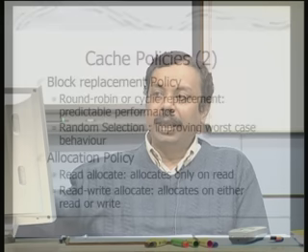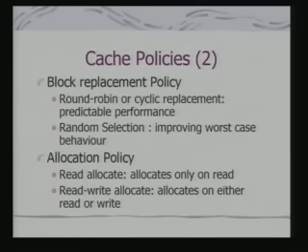So, in that case, even when there is a write operation, you would like to allocate that block in cache. Otherwise, a typical instruction execution would necessitate a read allocate policy. Now, these policies are always a part of what I call hardware policies, implemented in the hardware.